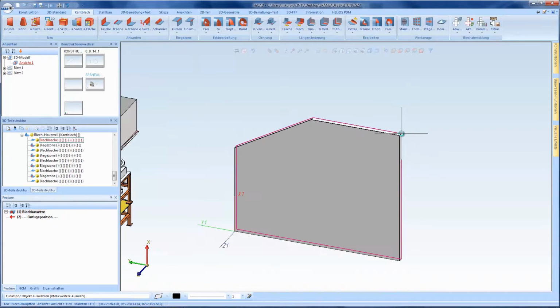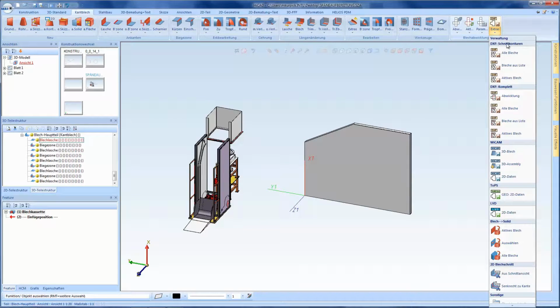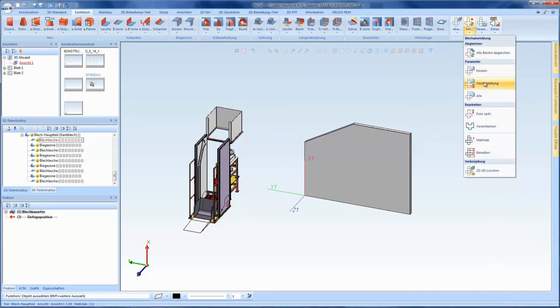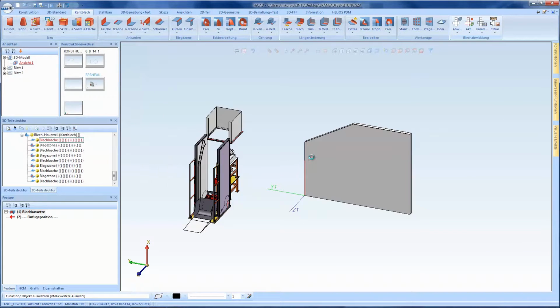Another improvement concerns the development. In the past, you could extract section contours completely in one go, so all sheets in the drawing were written into a directory in one go. However, as I said, only the section contours. In the Service Pack 2, there's the possibility to extract the complete contour plus the information it includes. For example, bend zones, bend radius, punching tools, whatever it includes. This means everything you have defined before in the default settings. This will also be written in the external DXF.